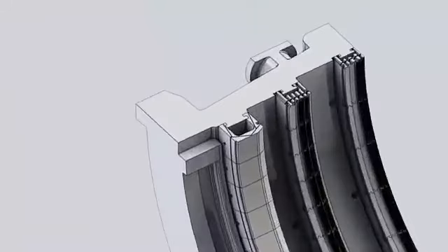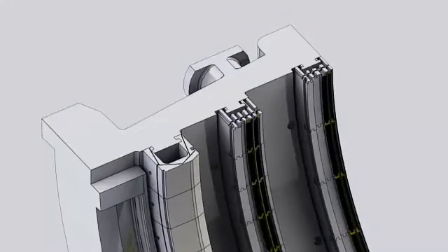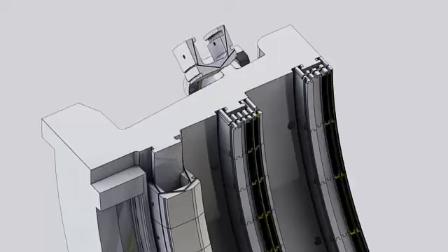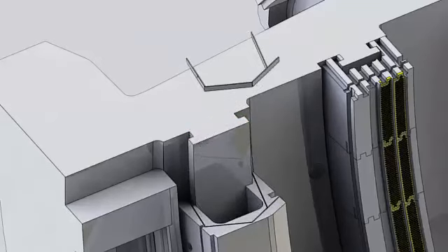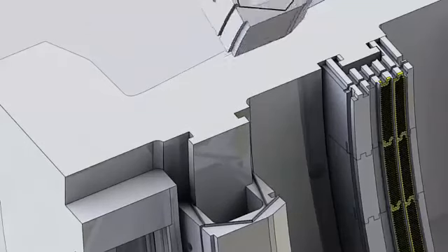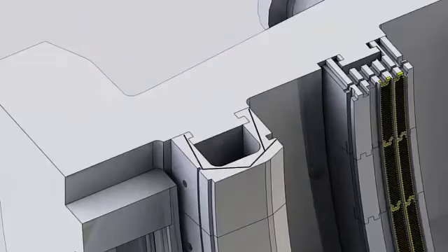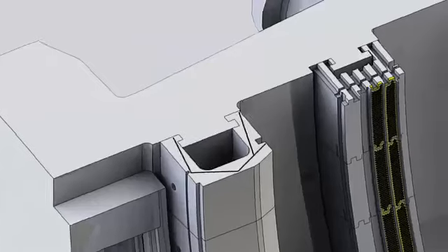Unlike the compressor blades, the turbine rotating bucket tips don't run directly against the stator casing, but against curved segments called the shrouds. The primary function of the shroud is to minimize the tip leakage. These shrouds are attached to the turbine shell by sliding onto the T-hook arrangement machined on the turbine shell. Joints between first stage shrouds are sealed by cloth seals. Shrouds are maintained in the circumferential position by radial pins from the turbine shell. The first stage shroud is coated with thermal barrier coating to withstand the extremely high temperatures at this stage.